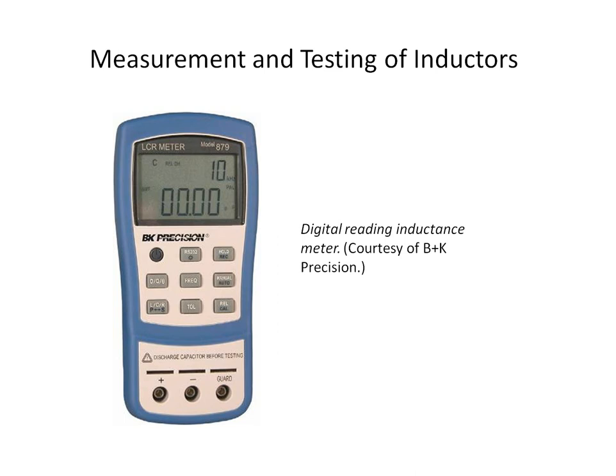Inductors can be measured by what we call an LCR meter. LCR meters are specifically made to measure inductance, capacitance, and resistance. And again, they're called LCR meters. So to measure the inductance, we would just plug it into a meter such as this, and it would tell us what the inductance of that inductor is.